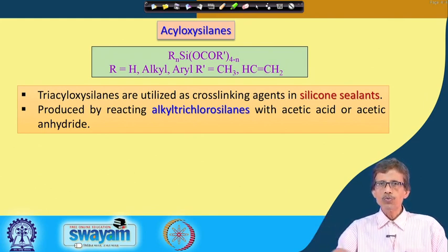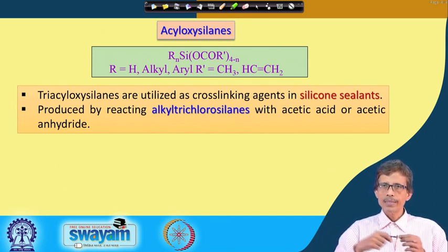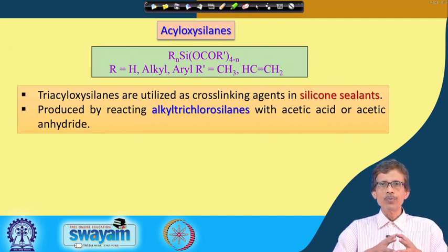We can use it as a very useful sealant, and sometimes it can so happen that, as we have seen, you have vinyl function, and in presence of air, basically if you can have the corresponding epoxy function as well as vinoxy, the vinyl epoxy resins we all know. So that vinyl epoxy resin in presence of oxygen of the air can polymerize further, and that particular sealant, when it is in absence of air within the tube, is in the liquid form or in some emulsion form. When it comes out of the tube and it goes for the reaction along with that air oxygen, it can be solidified. So, it can seal that particular part.